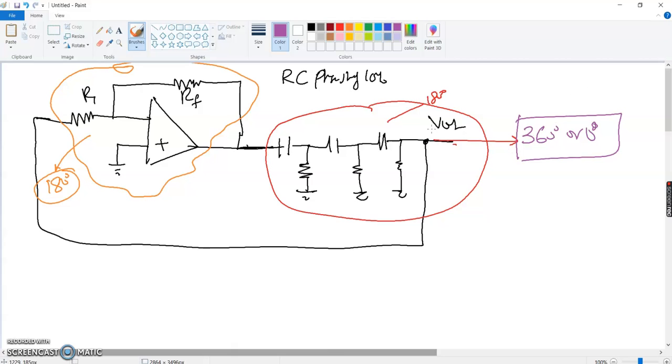All right, so there are a few important formulas that you would know. They have a derivation, but I'm not going to derive them, I'm going to just quickly write them down so that you can understand and use them. If you want to design at a very specific frequency, the formula for frequency for RC phase shift oscillators is 1 over 2 pi root 6 RC. I know there would be a concern in your mind about where you get the root 6. You can probably find a lot of videos and notes available for the derivation of this root 6. It's just about taking the circuit over here and then carrying out the nodal and loop analysis to figure out the value of the constant.